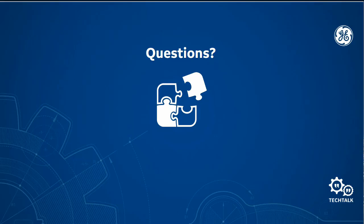The second part of this question is around what's the difference between RMS and the phasor quantities. So RMS obviously stands for root mean square. Now, we often take that to mean the peak of the voltage or current, peak of whatever waveform, divided by the square root of 2. That's one way to find it. That's the way to find the RMS value for a perfectly symmetrical waveform. But the RMS quantities are actually related to the area, the integration of the waveform, the area under the waveform. So since it's related to that area, it is going to include any harmonic content. So an RMS quantity would also include the harmonic content.